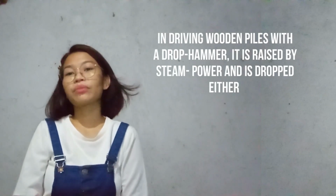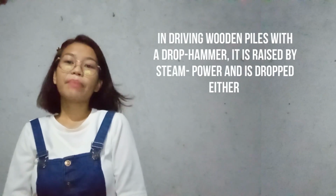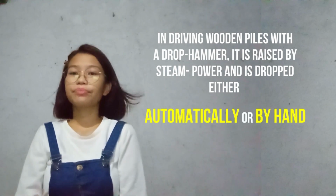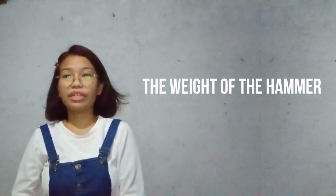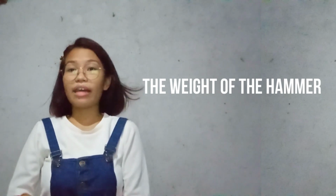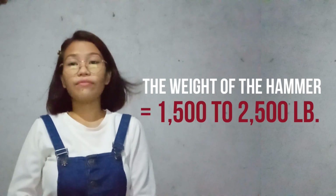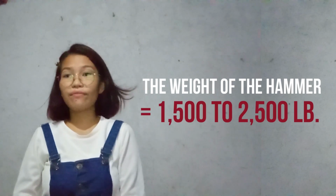In driving wooden piles with a drop hammer, it is generally raised by steam power and dropped either automatically or by hand. The weight of the hammer used for driving piles for building foundation is usually from 1,500 to 2,500 pounds.